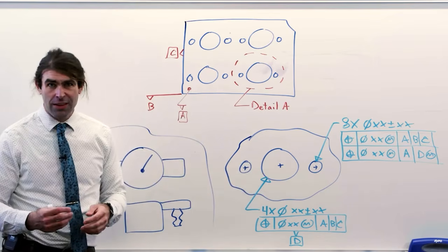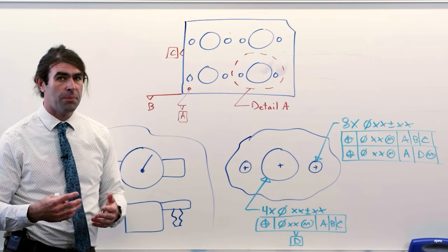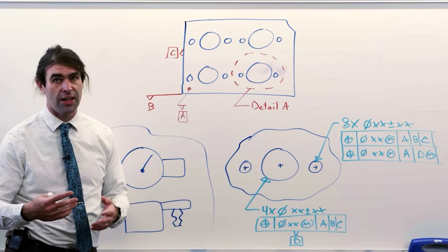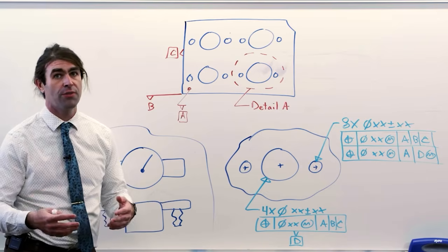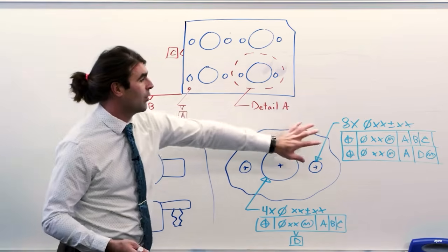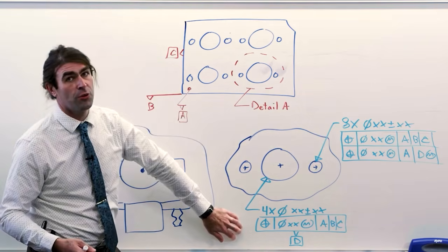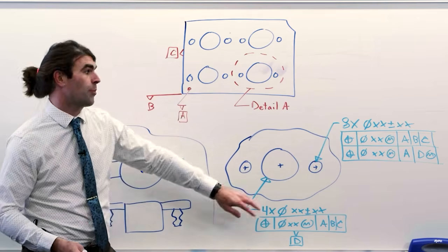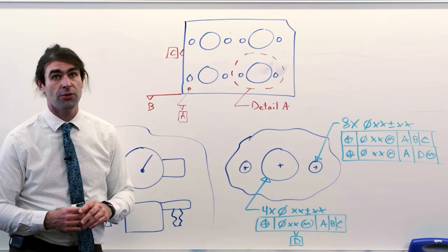I think the ASME standard in 2009 kind of messes this up in the individual section where it's talking about datums individually. It shows it as, say it's got this, it shows this, and then shows the detail view as also being 4 times. But when you repeat a detail view, you're repeating all of the features within it.